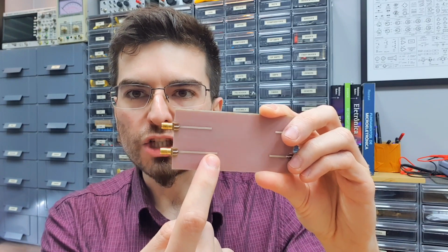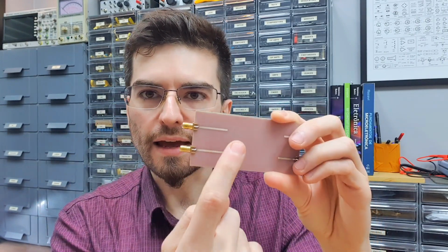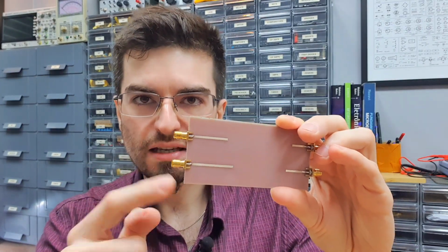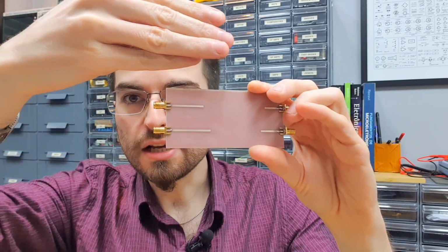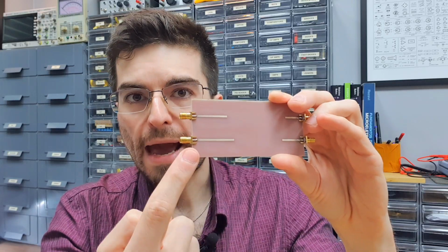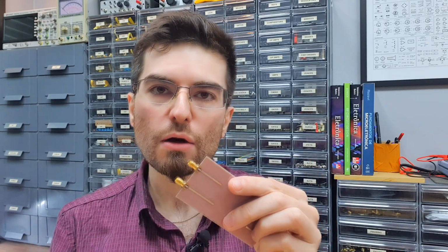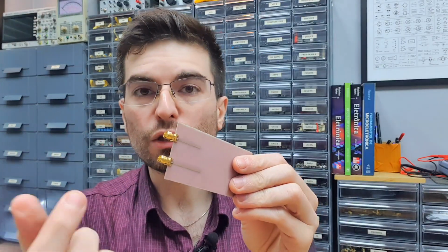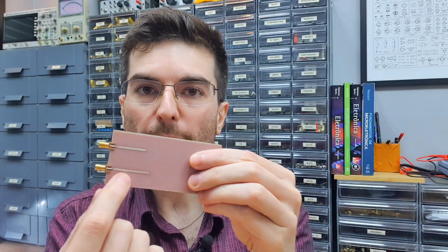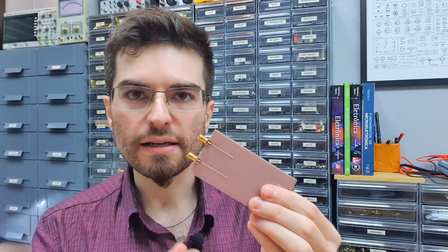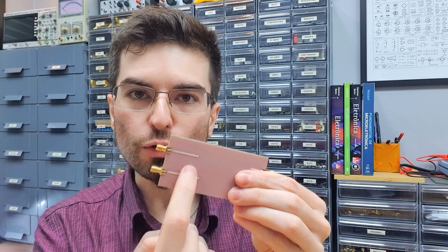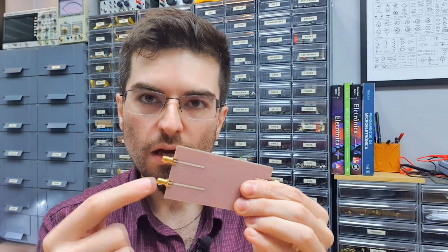But why use a pair of microstrips? We can consider just the increment in length between both lines, canceling in some way the effects of the SMA connector. Because imagine that we just measure one microstrip, measure its electrical length. This hypothetical measurement would include the electrical length of the SMA connector also, and also the electrical length of the transition from the coax medium to the microstrip medium. By having two lines, in theory, we can consider just the increment and cancel the effects of the SMAs.